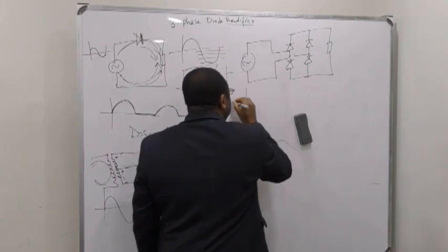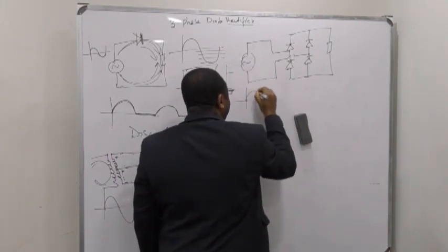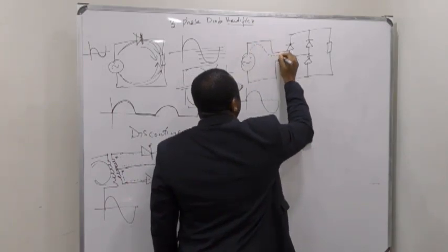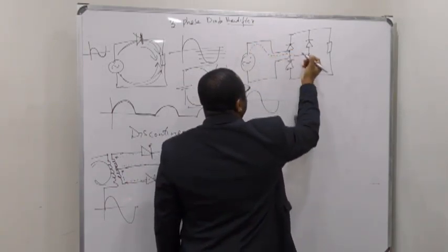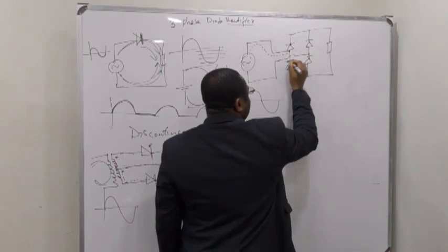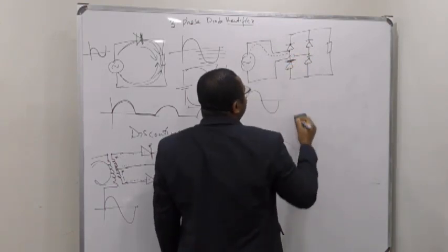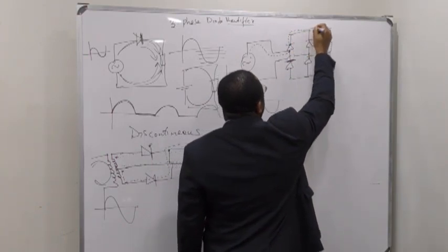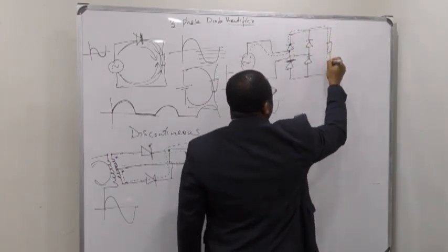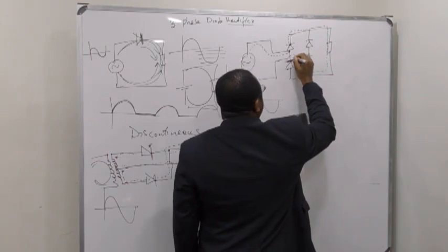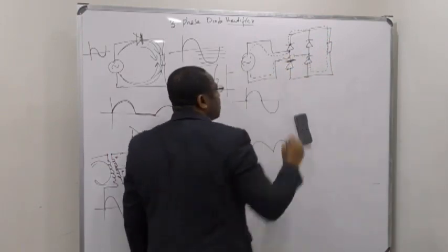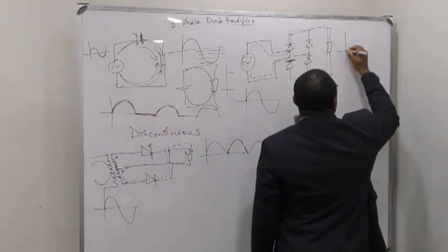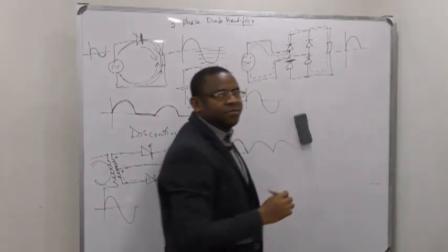Now, the first half cycle, remember this will be going forward. So now let's see, forward, first half cycle, go like that. It comes to this point. It cannot go down because here the diode is reverse biased. So it cannot enter here, it goes to the load. Like that, now it comes back. So that means this load, we see the first half cycle positive.